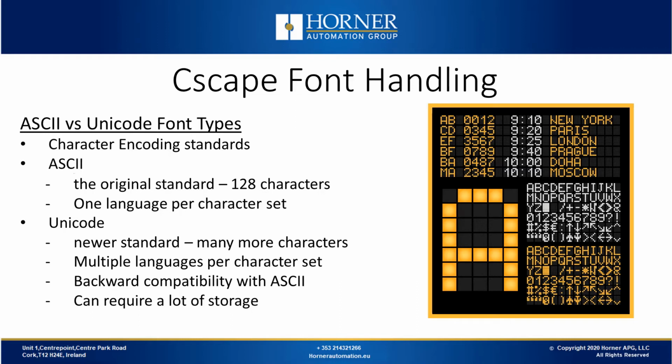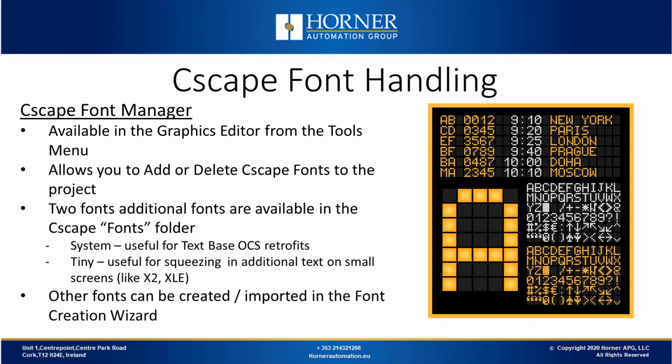Because of the high number of characters per character set, Unicode can require a lot of storage. The OCS has a limited amount of space to store custom fonts. Let's talk about the Font Manager tool. This is available in the graphics editor from the Tools menu and allows you to add or delete additional Cscape fonts to the project. Cscape fonts reside in the font folder and they have .fnt as their file extension.